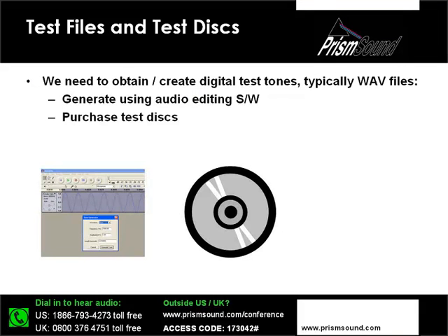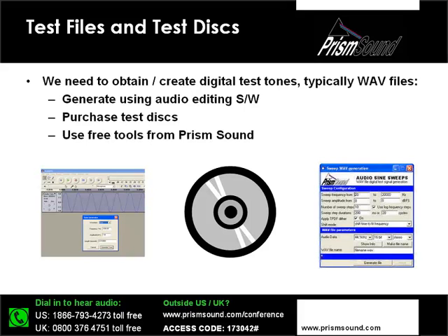Another option would be to use a test disc, and there are quite a number of test discs available on the market, and they contain lots of useful test tones that could potentially be used for this purpose, either for testing a disc player directly, or you could lift the files off the disc and save them onto the device that you're testing. The final option that I want to mention here is that Prism Sound does have a freely available tool for creating WAV files, and I'll show you a little bit more about that particular application a bit later on, but it's a very useful tool that allows you to generate your own test files that meet your own specific requirements very easily and very quickly.